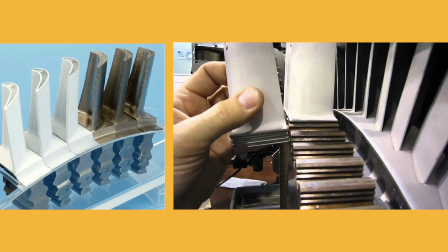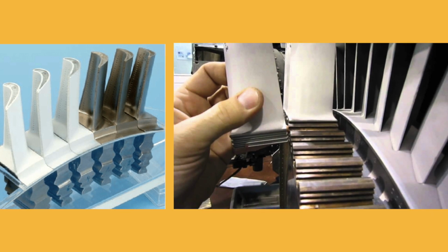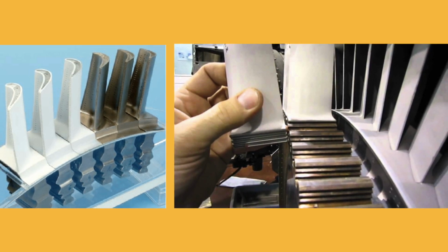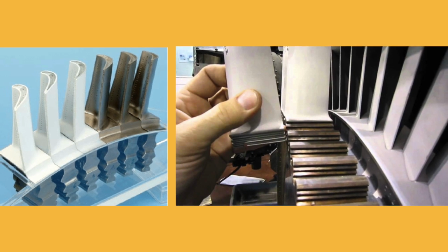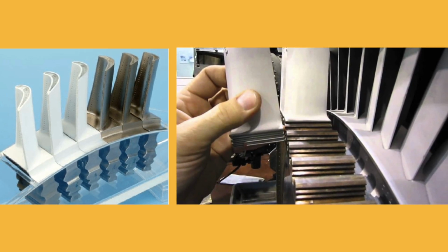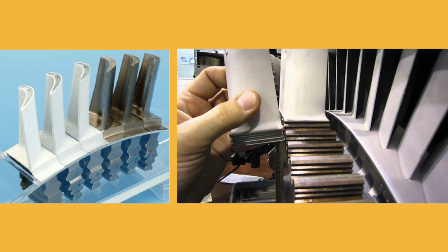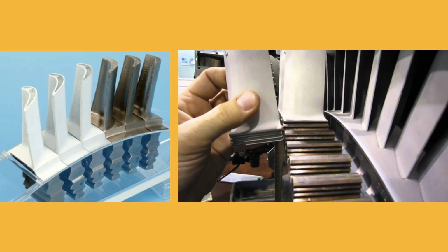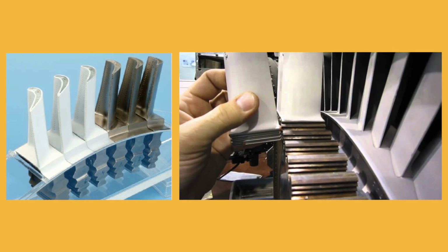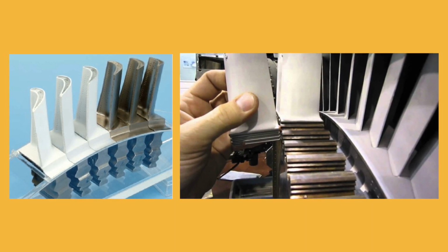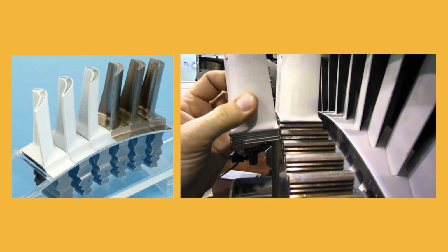Every blade extracts the same power as that of an F1 car engine. Every blade experiences a centrifugal force equivalent to the weight of a double-decker bus. The blades rotate at 1.5 times the speed of sound. In addition, the blades are required to operate at 1700 degrees Celsius. It is vital that turbine blades can withstand these high temperatures and large stresses.